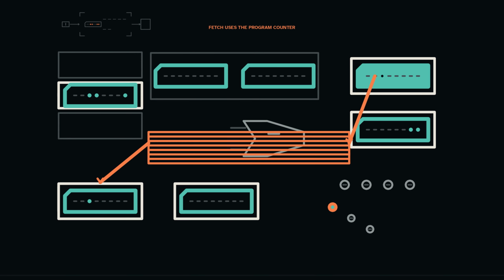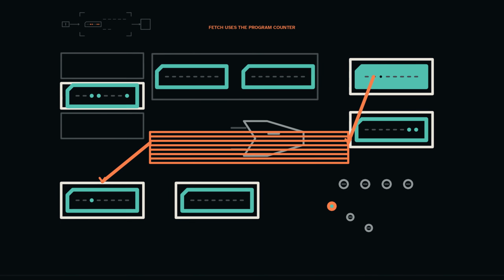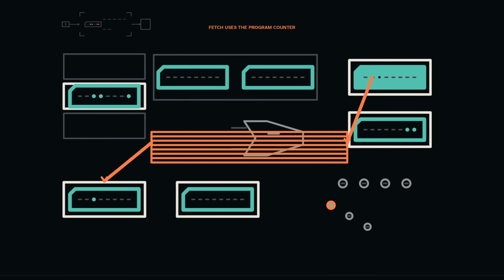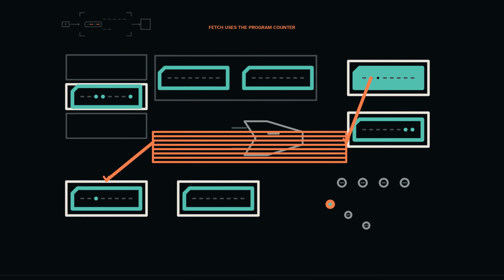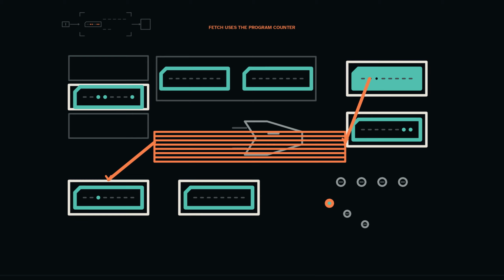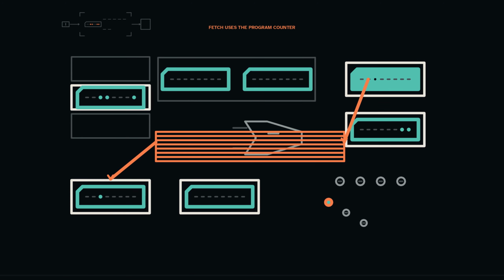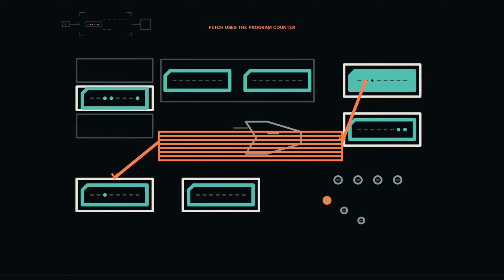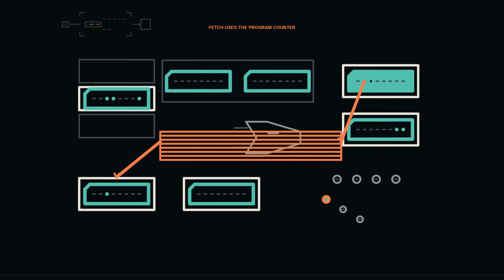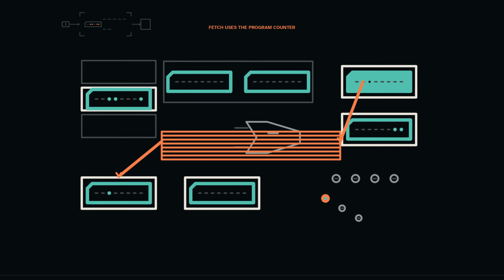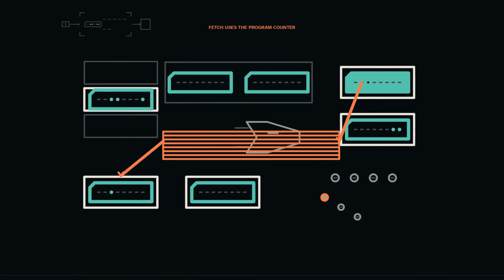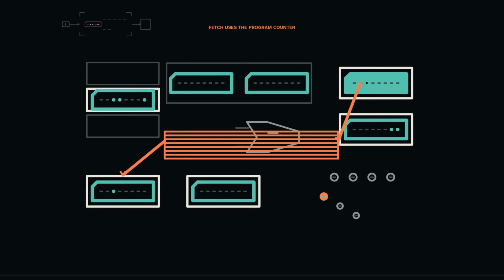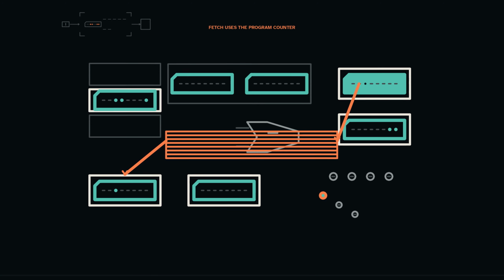At reset, the next state is fetch 0 address. Its control permissions allow PC to drive the bus and MAR to capture. After that edge, the controller advances to fetch 0 read, whose permissions allow selected memory to provide a byte and MDR to capture. Think of a railway timetable only for the relation between named stages and permitted actions. Stop before intention. The controller is finite state and logic, not a dispatcher thinking about the instruction.